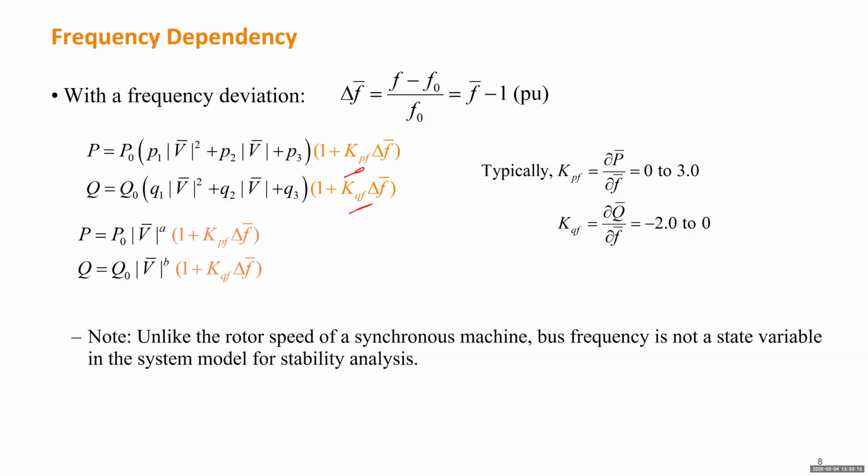Remember the difference between a state variable and a non-state variable. A state variable cannot change instantaneously because there's a control system or time constant associated with this variable that stops it from changing instantaneously. There's some time constant such as tau. Tau means it takes a time of tau to decay to 37%, right?